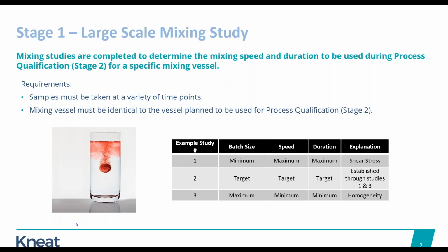So I've seen a great deal of different studies. And when we're in the room, we are looking to make sure there's no splashing, there's no steep vortex in the mixer, and there's no foaming. If we see any of those things, that is a bad sign, and there might be something going on with the proteins in the drug. They might be breaking down. So if we see something like that, action would need to be taken for that to be reassessed and some of the parameters changed. So that is one extreme there.